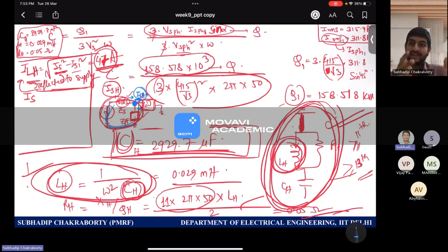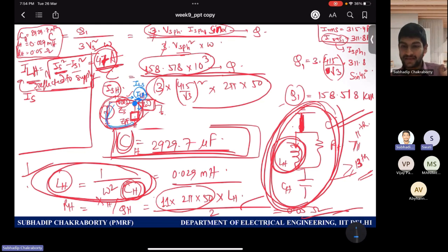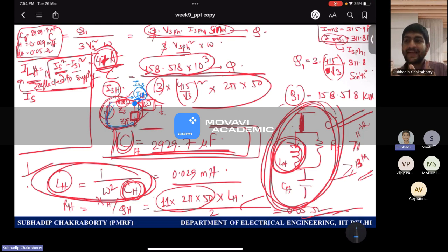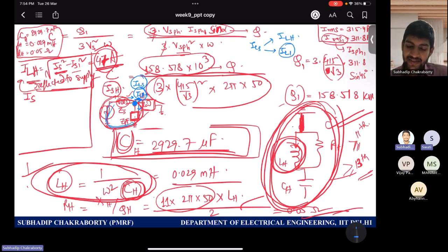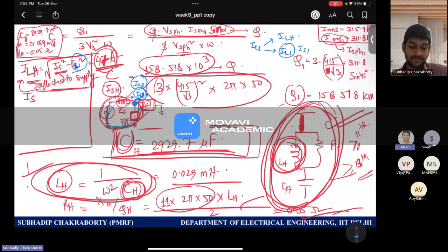All we did was reflect the load harmonic content current totally to the supply side, which I denote by ILS, for example. Supply reflected load harmonic. Now, this supply reflected load current had two components, one fundamental and another harmonic. So ILS was built of two terms, ILH and IL fundamental. IL fundamental is what I am denoting by IL1, because still we don't know what is the fundamental of the supply.